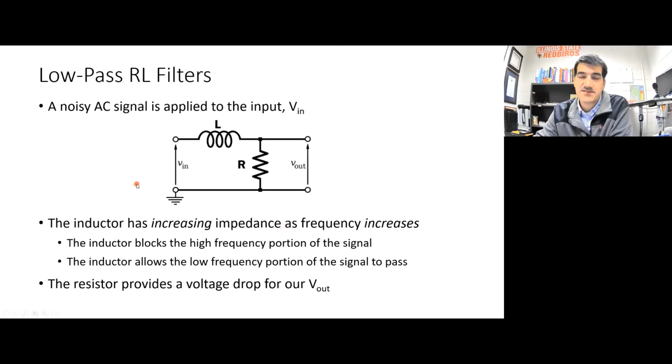And this is a circuit diagram that's kind of similar to the RC low pass filter, but go back and check and you'll see that they're a little bit different. Remember, the RC low pass filter had a resistor here and a capacitor right here. So be careful about the placement of these components.